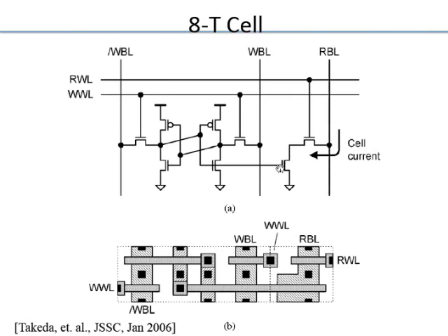If this voltage is 0, there is no current. The bit line remains floating at VDD. But if this voltage is 1, then this discharges and the bit line falls. So you can transfer the data from within the cell to this bit line.